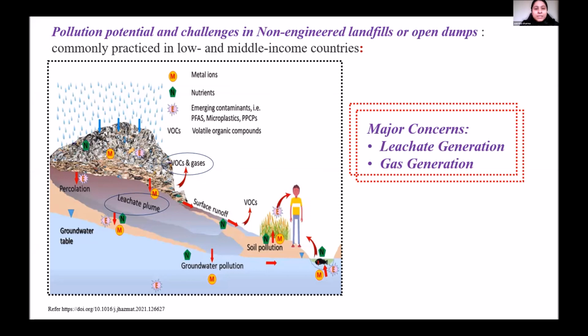In a municipal waste facility, the most pressing concerns for environmental or municipal engineers are leachate generation, first of all, and landfill gas generation. Which is more contaminating, the leachate or the landfill gas? There is no debate on that. It's equally harmful for the ecosystem, because once leachate is generated, it contaminates the soil and the groundwater, and the nearby ecology is destroyed because of excessive eutrophication. The environmental risk associated with a landfill is too much. It mostly occurs in two phases, liquid and solid.